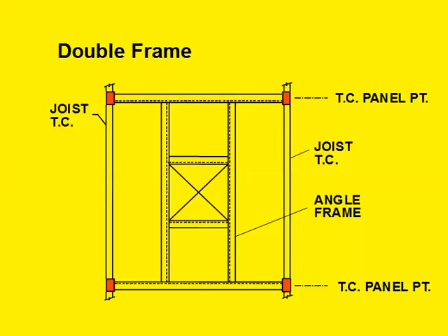Now here I show a top chord panel point. The problem that you and I have when we're designing something is we don't know where the top chord panel points are. We don't know where they're physically in the field. So if you use this, yeah, you might get lucky. Most, well, don't make a note on this, but most K-series joists, if they are, let's say, more than 20 inches deep, the panel points will be 24 inches apart, because that's the maximum the joist people can use without adding bending into the top chord. So most of them will be 24, but you don't know for sure.